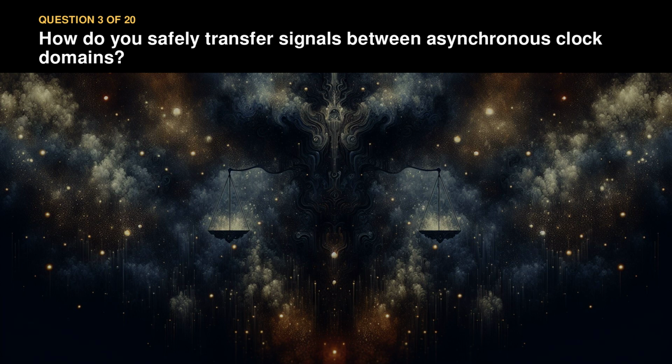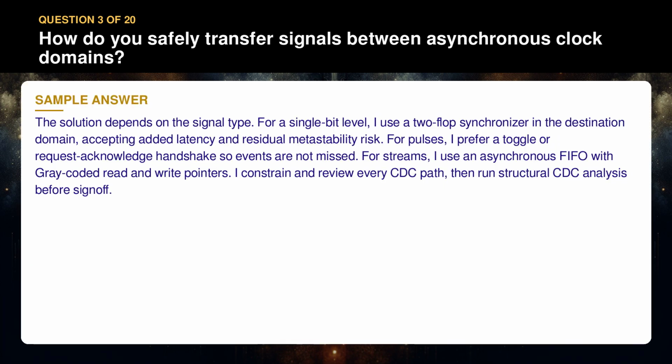Question 3. How do you safely transfer signals between asynchronous clock domains? The solution depends on the signal type. For a single-bit level, I use a 2-flop synchronizer in the destination domain, accepting added latency and residual metastability risk. For pulses, I prefer a toggle or request-acknowledge handshake so events are not missed.